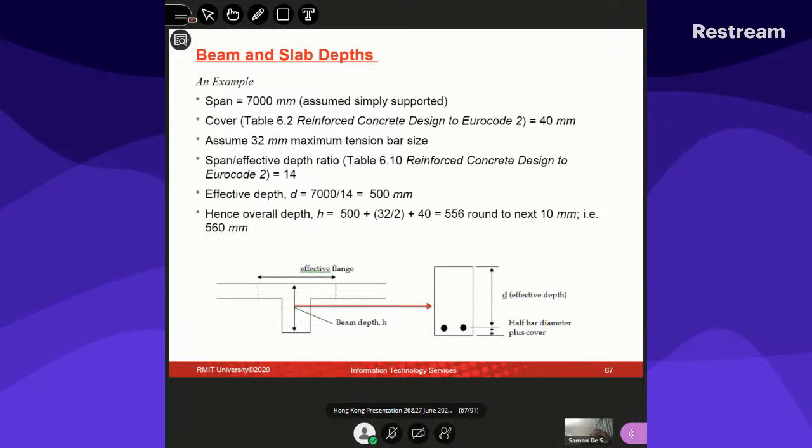Okay, I'm pretty sure you will be perfectly fine to do a simply supported or continuous member. You can use Space Gass to model that entire plate if you want, with the beams and also using plate elements. Your entire thing can be modeled there, and then change the sizes, and check deflections for a start, and then see what sort of values you get.